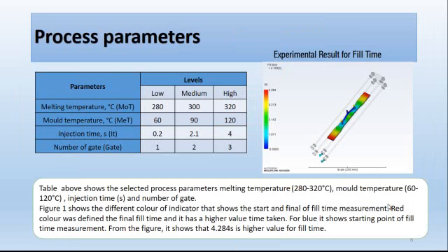This table shows the process parameters, which are the melting temperature, mold temperature, injection time, and number of gates. And then figure 1 shows the different color indicator that shows the start and the final of the fill time measurement. From the figure, it shows that the highest fill time is 4.284 seconds.